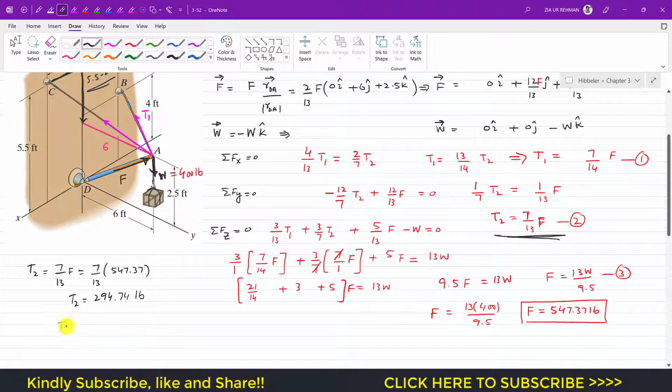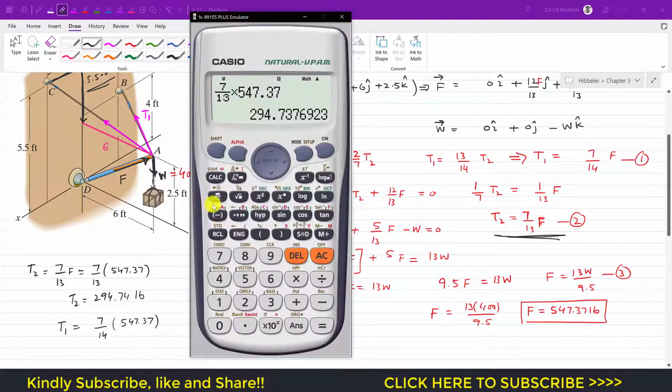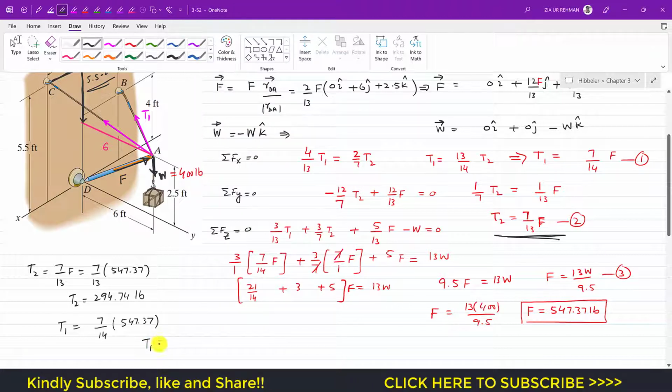And similarly T1, from that equation 1, T1 is 7 divided by 14 into F. Again F is 547.37. This is 7 multiplied by 547.37 divided by 14. This gives us 273.69. So T1 is 273.69 pounds.